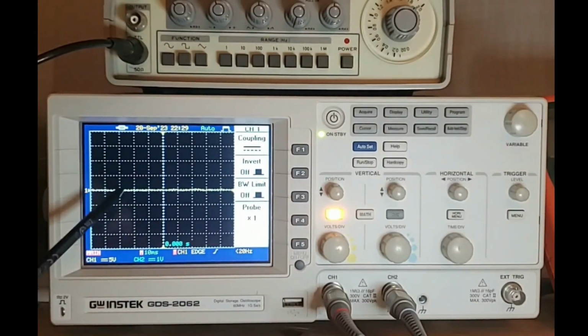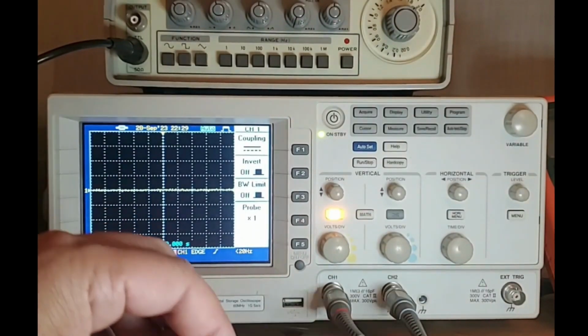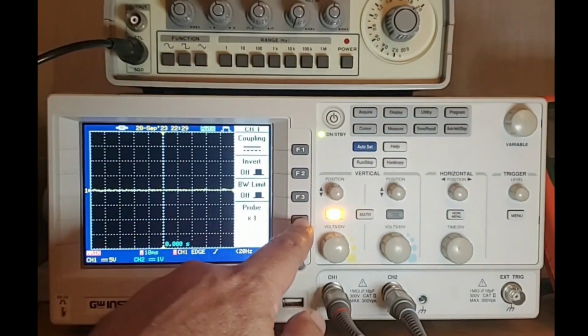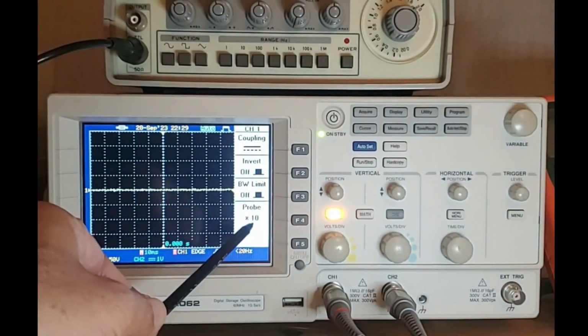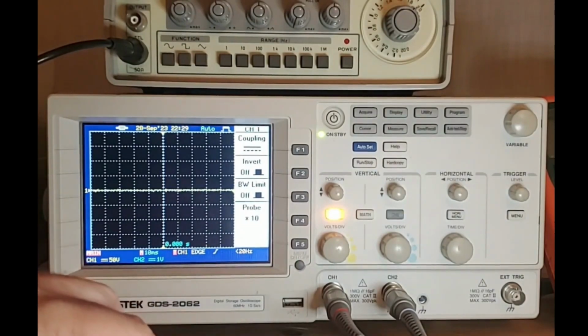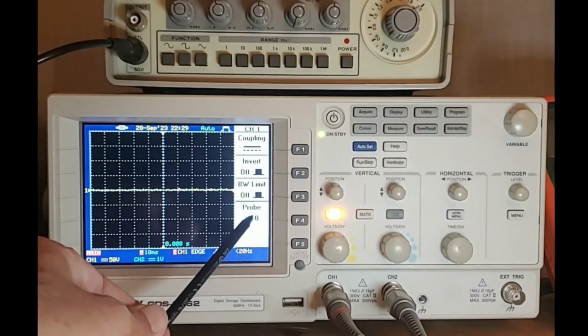However, on the screen, it will look like that I'm measuring 5 plus 5, I'm measuring 10 volts. But we have divided it by 10 using the probe. So the actual voltage, for us to read the voltage, what we can do is that we can use this factor over here just to let us know that we have actually divided the voltage by 10 using the probe. So therefore, we will multiply by 10 over here.